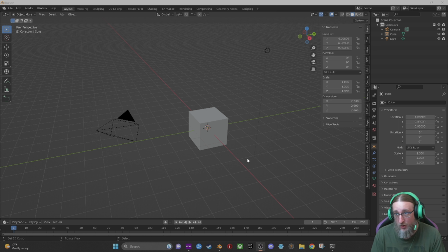So normally, because a subdivision surface modifier is going to be the next step, what I'll do is click on the little tab that's down here. After you do subdivide, you'll see a little tab that pops up that says subdivide. And I'll turn that up to, normally for me, between 20 and 50. 50 for the highly detailed ones and 20 for the lower detailed ones. So I'm going to do 30 here.